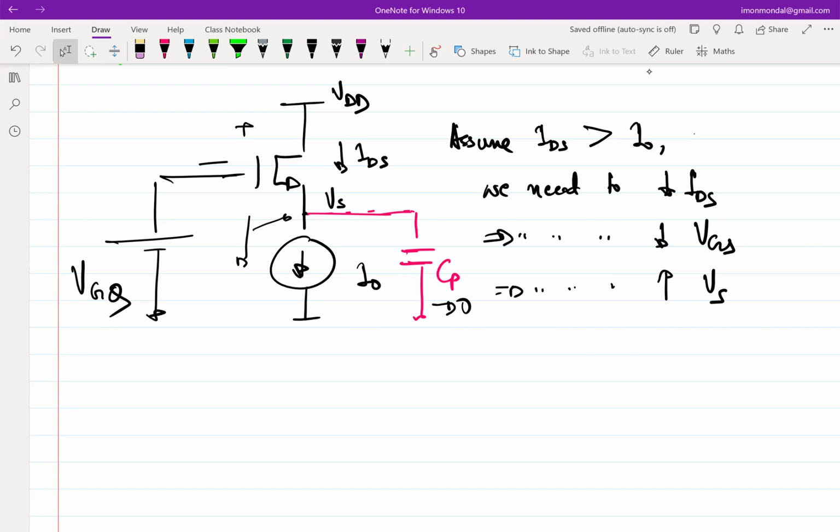So whenever we are trying to figure out whether there is a feedback or not, in this case negative feedback or not, what is the core principle of negative feedback? I presume you are doing negative feedback in 250, right? Let's say you have a network, you disturb the network, the negative feedback will ensure that the network comes back to its original position. That's the whole purpose of feedback. It keeps the working tight. You disturb anything and it comes back. The system comes back to its original operating condition, or at least a similar operating condition.